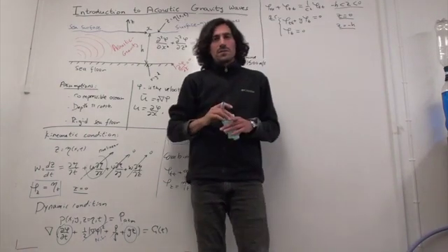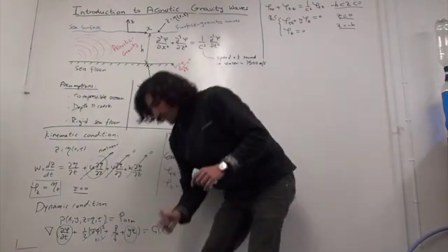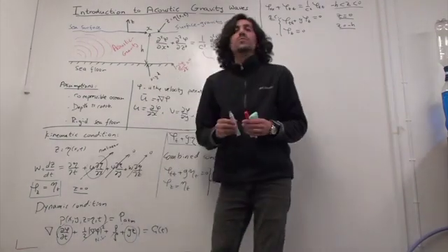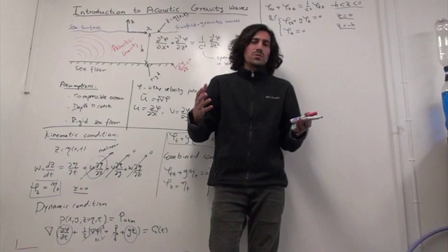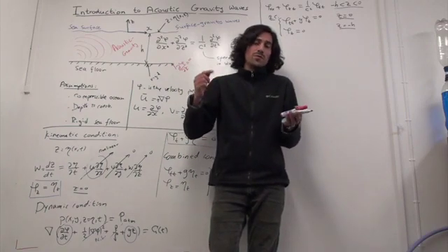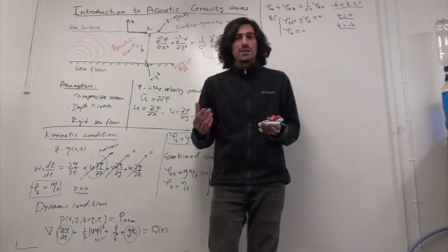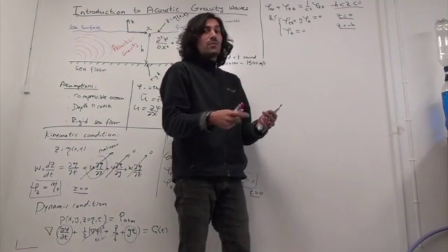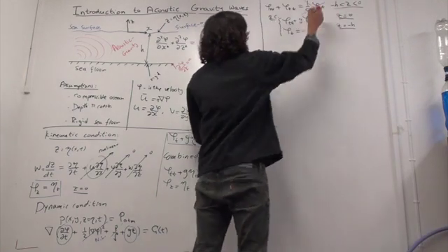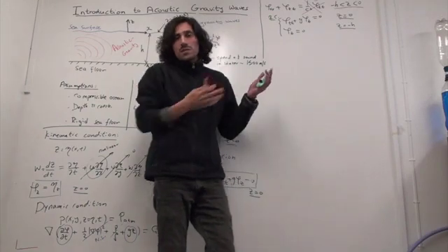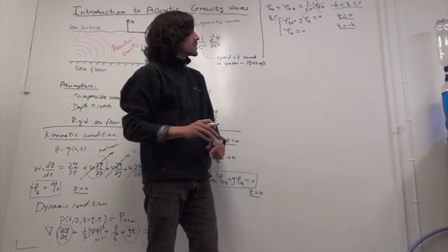Now at this stage I want to make one further simplification. So basically we're not going to solve the wave equation initially, but I want to do that. I'm going to assume that the water is incompressible. The meaning is that if you try to compress it, if you make one movement in one place, the flow in all the places would react instantaneously. Which means, in other words, the speed of sound is infinitely large. If the speed of sound is infinitely large, this term goes to 0. So this is 0, which means we don't have the wave equation. This is the Laplace equation. It's a different equation, but we're going to solve it. It's going to give us a nice solution for the gravity wave initially.